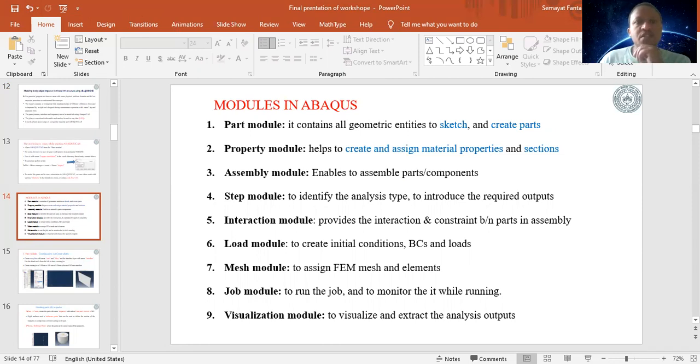Then okay. Then the next is go to special inertia, create point mass with inertia, then point mass, continue, show the point where we are going to assign mass, and then the isotropic mass, let it be 2 kg.